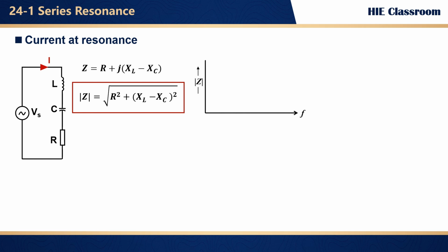When the frequency is way below resonance, the reactance is dominated by XC and is really big. As it approaches Fr, it drops down to its lowest point. Then, as the frequency goes way above resonance, the impedance shoots up high again because inductive reactance takes over.